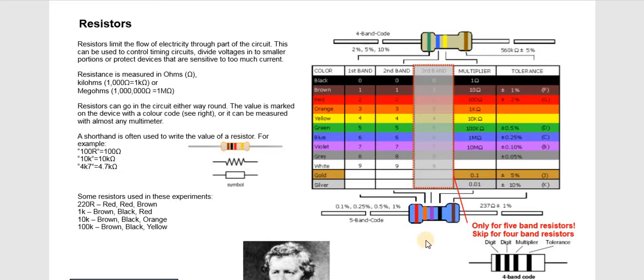So, for instance, let's use this 220 ohms resistor. It has a red, red, brown. So red is 2, the next red is 2, that's 22, and brown is 10, and brown being the second to the last color here. Whenever you see these three values, know that this is a 4 band, because the last value is not always mentioned when you want to calculate the resistance of a resistor, but because it's just tolerance, does not mean you don't use it.